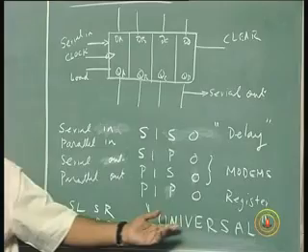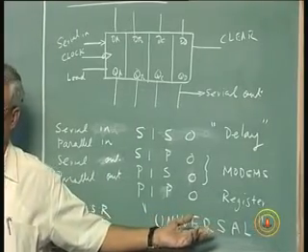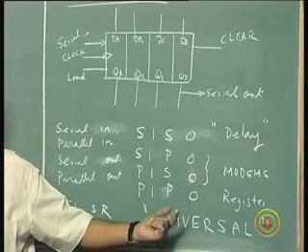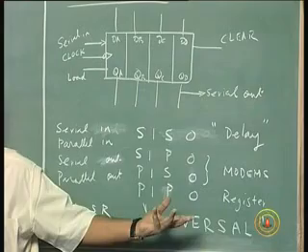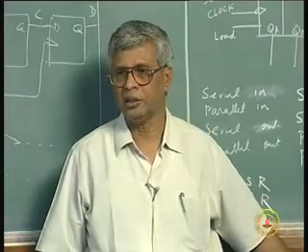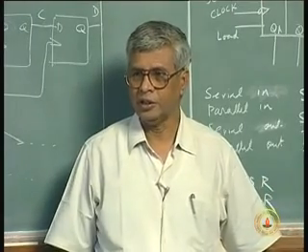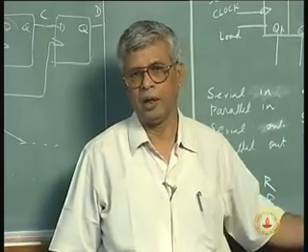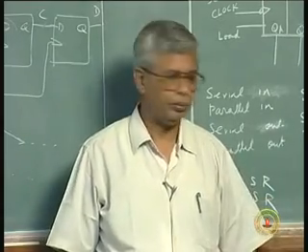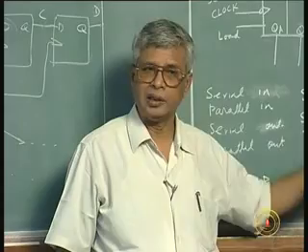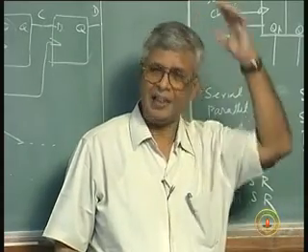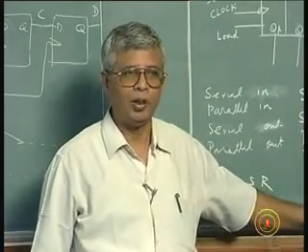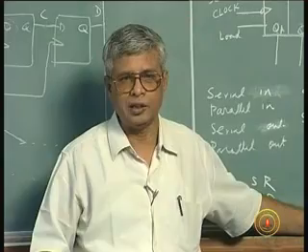Because they can do all the things that you want to, but of course not all of them at the same time. You have to configure it for one particular operation. You configure a shift register for a shift left operation, or a shift right operation, or parallel load and serial out, serial in, parallel out, and whatever. These are available in the market commercially, but you should know what is inside. Inside, after all, nothing. So I have reduced the myth of all these registers, counters, this, that.